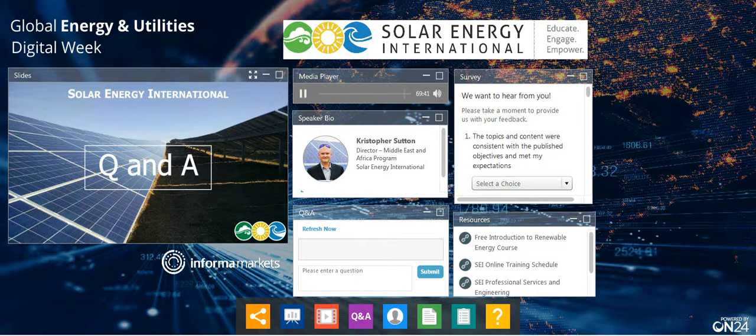For utility-connected normal systems or big power plant, solar farm type systems, one that's very commonly used in the world is called PVsyst, and it's really doing the production modeling. It's focused on energy generation modeling: the angle of the sun, the time of day, the location, the size of the array, tilts, orientations, all of that. Another really common one that's coming up is called Helioscope. Those are all grid-tied. There are others out there, but those are some of the big ones commonly used.